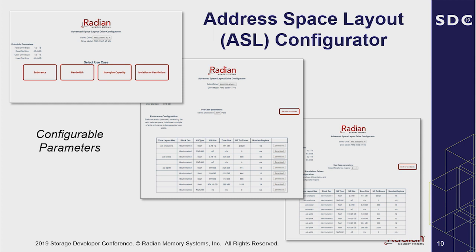Our zone drives are configurable based upon performance, endurance, isolation, capacity, and a range of other parameters. A higher bandwidth requires that more dies be included in the write stripe of a given frontier, which implies larger zones comprised of higher numbers of participating erase units. Isolation between zones requires that they be laid across separate dies. Increased endurance implies a smaller overall capacity due to increased over-provisioning.